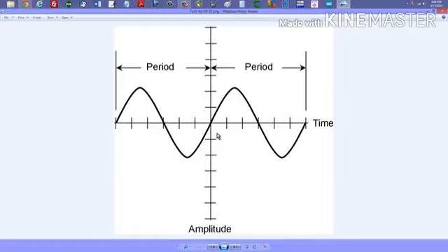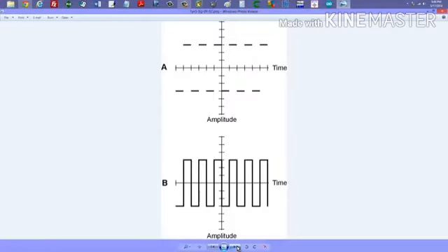1, 2, 3, 4, 5, 6. You can see that. And the amplitude or voltage, if this is 1 volt per division, looks like about 2.2 volts plus peak and 2.2 volts minus peak. So that is the simplest possible wave in electricity and electronics, and ideally it would be what came out of your wall outlets, although that's not always true.